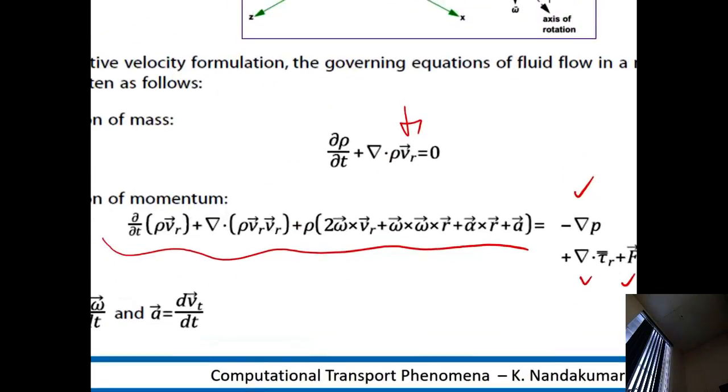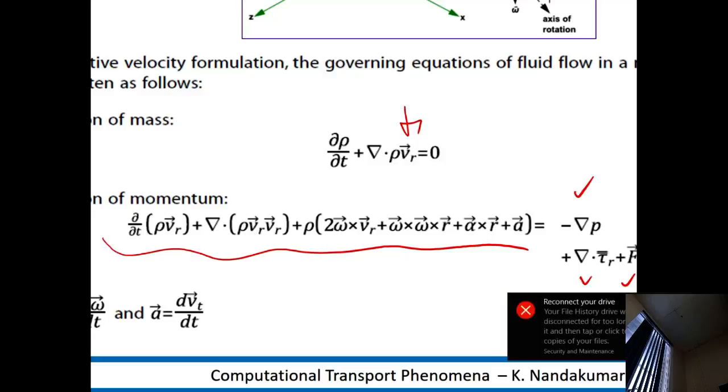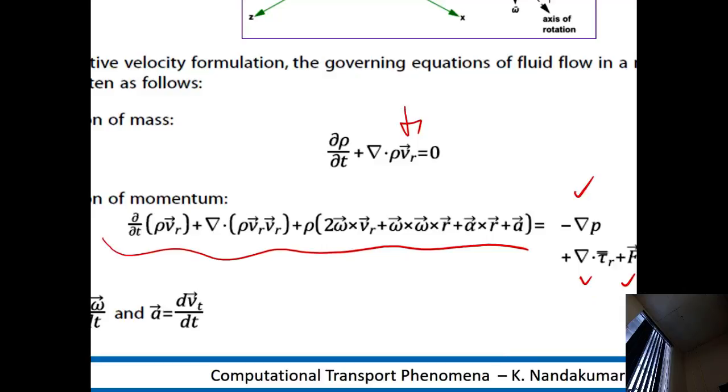So this is the equation in a moving reference frame that is solved by all these packages. Right? None of the terms on the right hand side change. On the left hand side, it gives birth to a lot of new terms. These are all the pseudo forces because you are in an accelerating reference frame. Okay, so these are all in terms of the moving reference frame velocity, and this is the acceleration, and this is the angular acceleration. Do you recognize what this term is? Omega cross R.